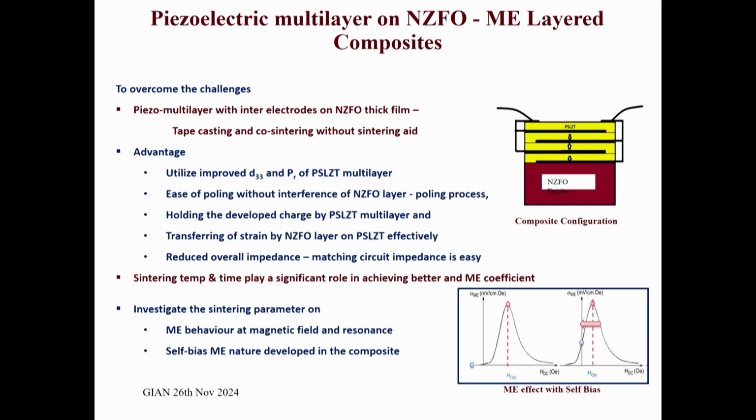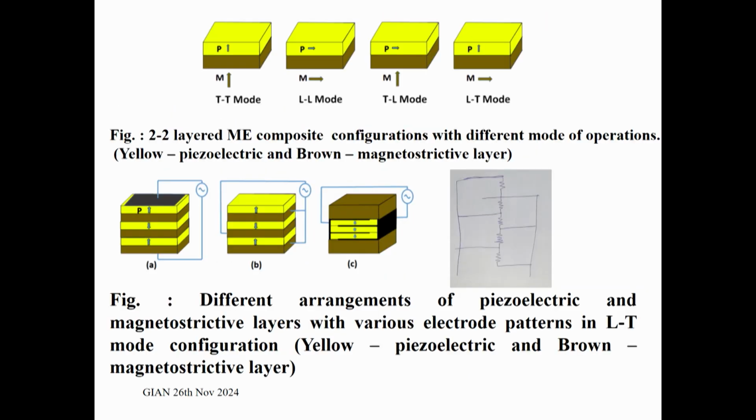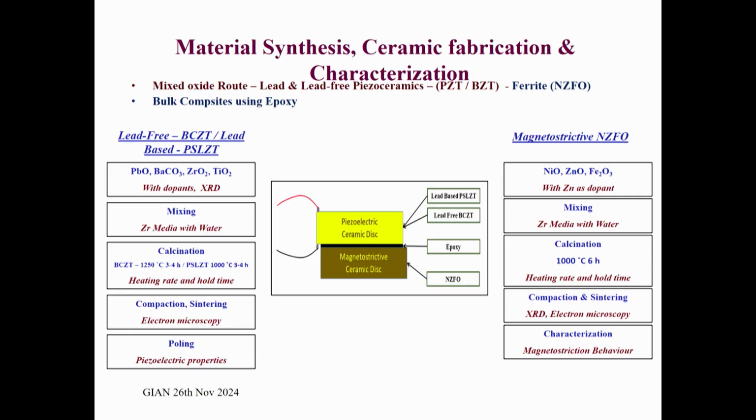In layered composites, this is the way we tried. So, where the different kinds of electrodes are, this is the arrangement we made. And yeah, this is the picture you can see. This is the schematic of the device we have made, and this is the diagram where you can see these two are electrically parallel and all these are mechanically in series with each other. This gives you higher piezoelectric performance.